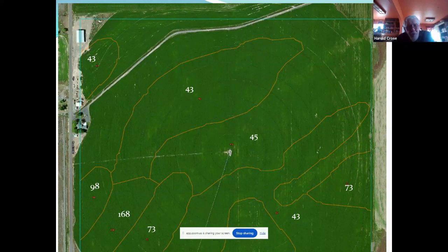You need to be physically able to go out in the field and ground truth what that soil type is, and it doesn't have to be extensive, but when you get more proficient at it, you can actually look at a field and stand there and read that landscape and determine where you would expect a soil break to be on sloping ground versus the high points in the field.